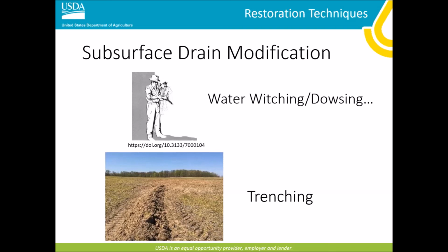Capping the tile, yeah. I'm going to cover that here in a second about ditch removal. The bad thing about capping the tile is there's potential, I'm assuming it's potentially a perforated tube, that the water will still be wanting to be pushed out of the perforations from the head upstream of that tile. So really removal of that tile for 50 foot, which I'm going to cover here in a second, is really the minimum, depending on the soil type that's there, to stop that tile flow.